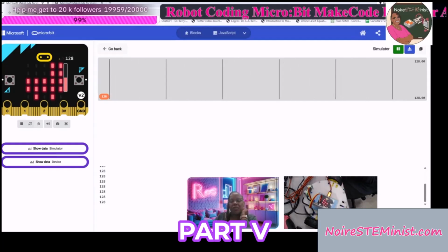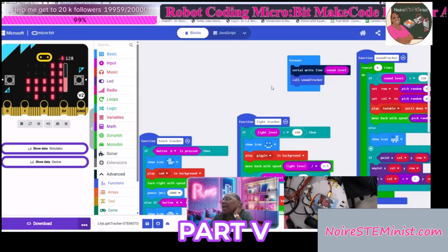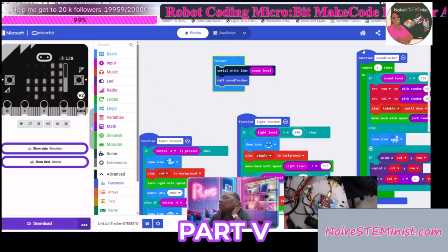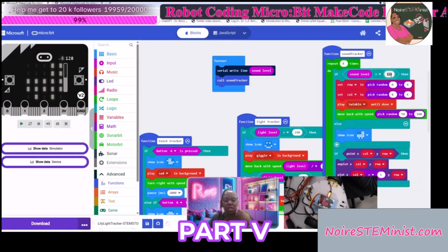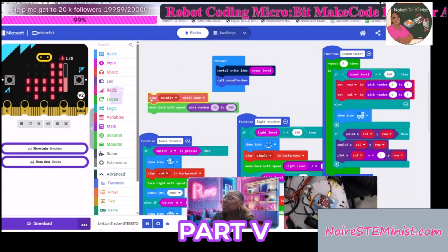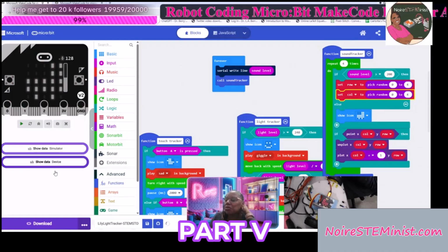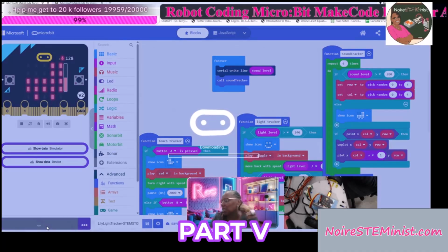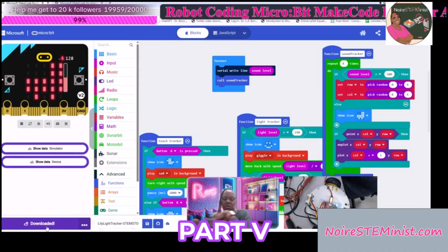All right, I have got to figure out how to get a better number out of here. So let's go back in here, and I am going to change my sound tracker to a higher number. Like, let's say I do 200. I'm going to change it to 200. And now, just because I need to figure out why it's making noise all the time, I'm going to take this out for a minute. And I am going to download this, and I'm going to go back and read my sensor again and see if we can figure out why it's triggering all the time.